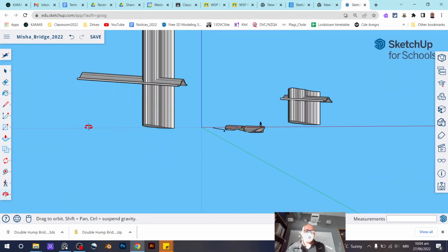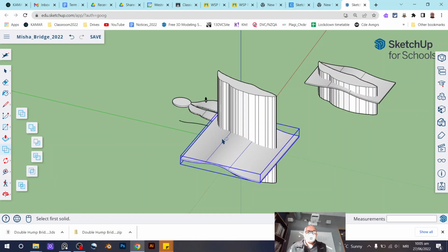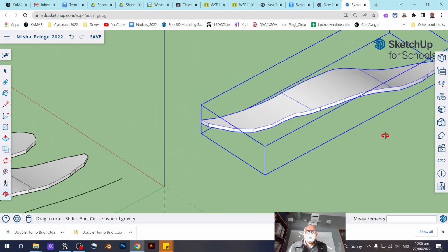Right, so now what I'm going to do next is choose my solid tool. I'm pretty sure I want this one. I want the intersection one. Basically what's going to happen is it's going to delete everything of this object except where the two objects intersect. So intersect, and this is the first group, that's the second group. And now it creates that shape there.